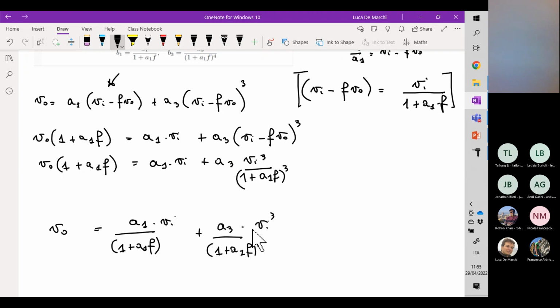What is also typical is that when we have the phase loss associated to a pole, half of it is occurring before the pole position, and so minus 45 degrees at the pole position, and minus 90 degrees after the pole position.